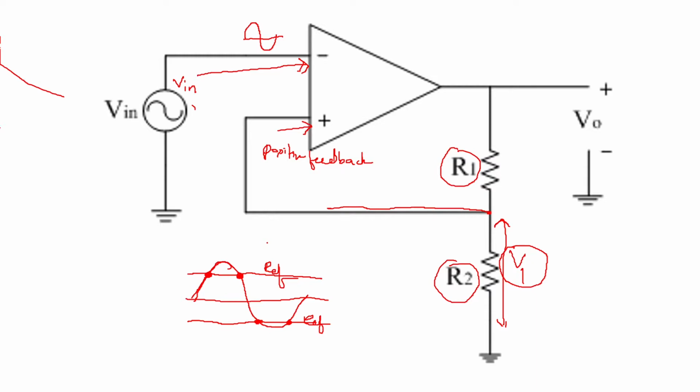One will be your upper threshold voltage UTP, and the second one will be your lower threshold voltage LTP. Those will be generated by using the output only, and because it is generated on its own depending upon the output only, it is called a regenerative comparator. Depending upon the comparison of both the inputs, the output is going to change its state in only two levels. Either it will be plus V saturation or minus V saturation. So it is like a square wave at the output.